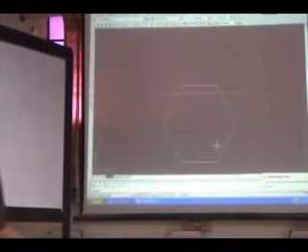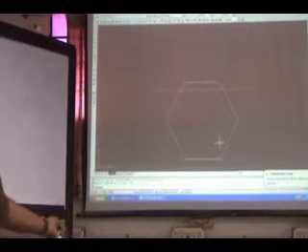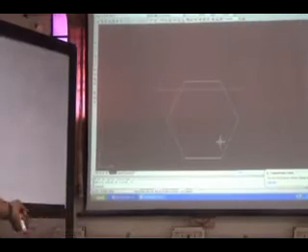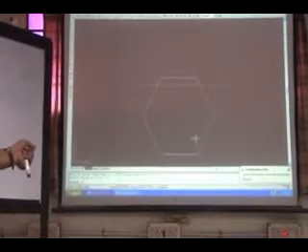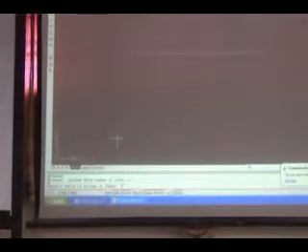It is wrong. If you want to erase it, you can erase it, like your eraser. Here you can erase it or delete it. E is nothing but erase. You see here, select object is asked. I am selecting this object. So still I want it smaller. I am going to draw it again. Second, that is 6 sides. Enter. Specify the center of the polygon.